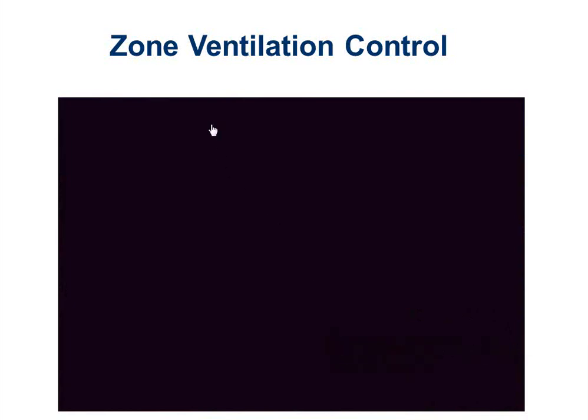There's an outside air handler on here and a 2-zone system, 2 damper zones. There's a CO2 sensor on the wall. As people come into this room and start breathing, the CO2 sensor recognizes that. It tells the VAV box, hey, bring in more outside air.